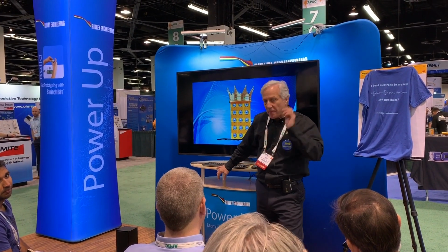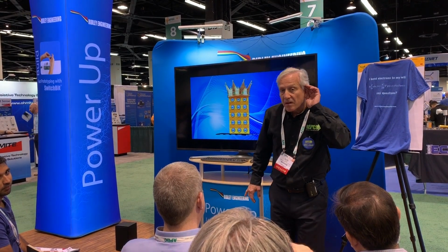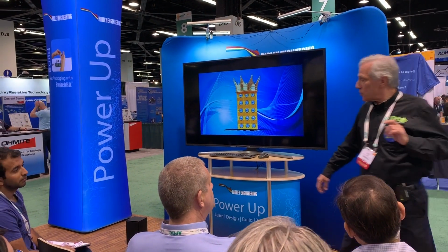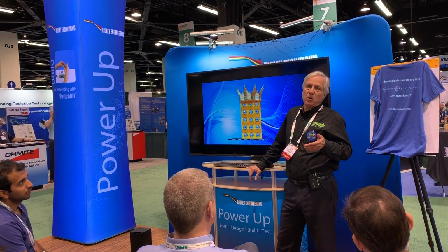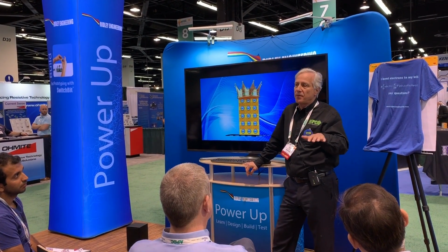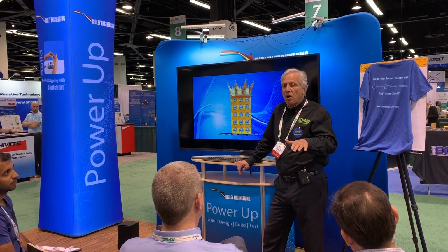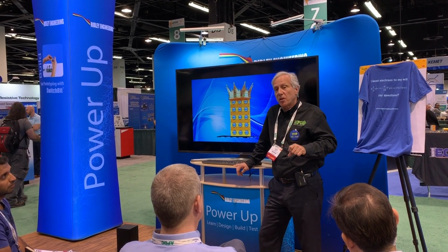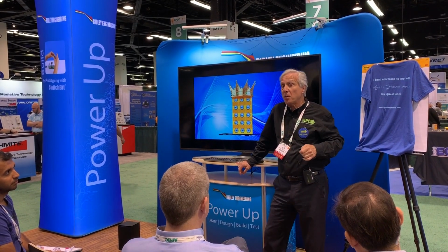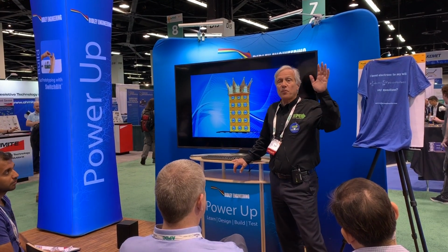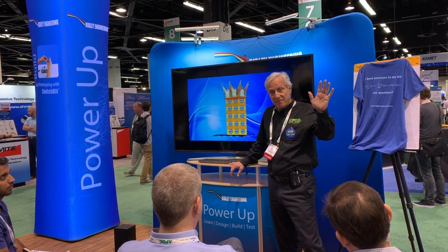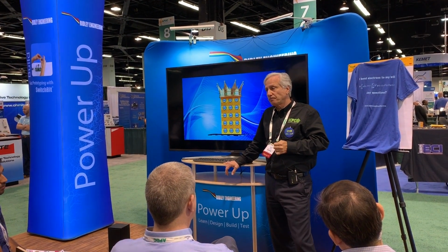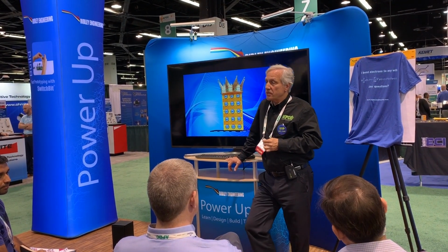We're all integrated on the PCB. What temperature do you limit when you're built on the board? Most PCB manufacturers will limit it to 105, some go up to 120. Our devices are all rated at 150, and it's hard to use 150 because of the thermal resistance to the board. But there are people in space that put them on ceramic. By the way, we run our device at 400 degrees C, not recommended. But GaN's limitations are primarily from solder.